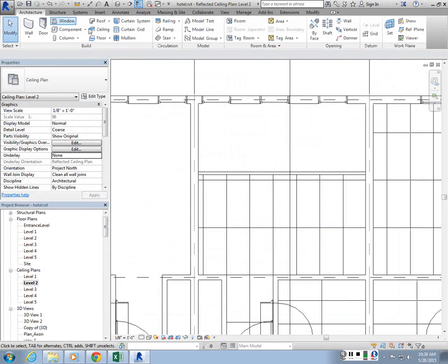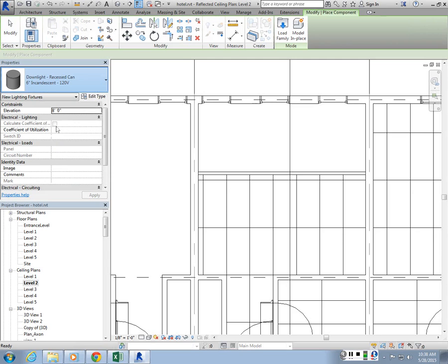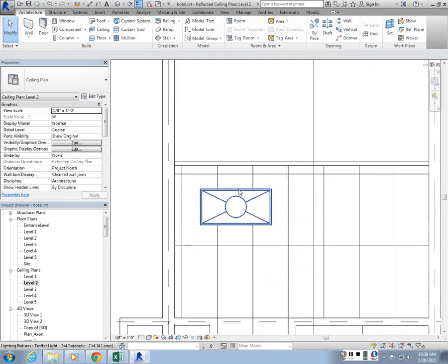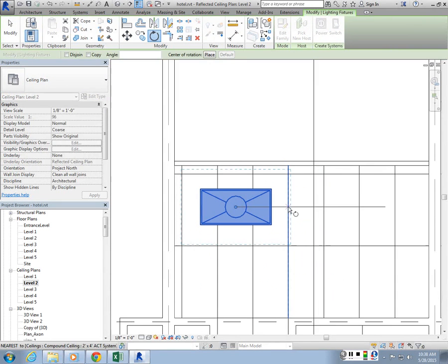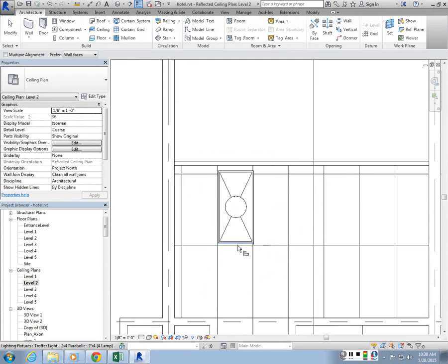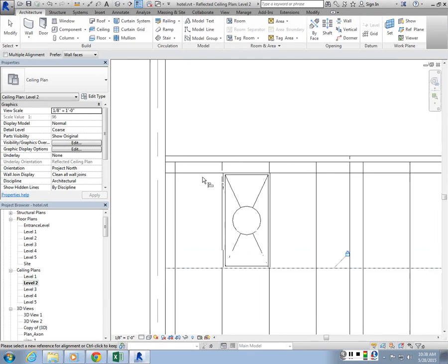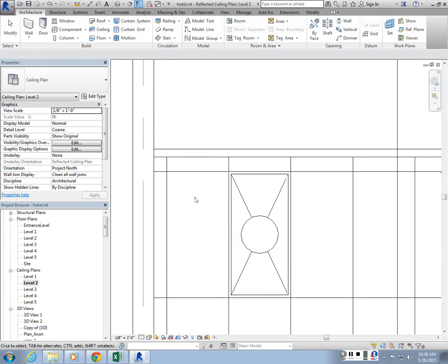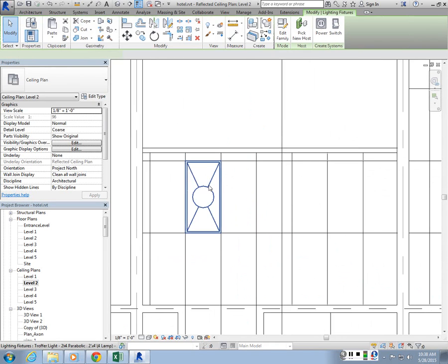And then if you want to include lights, you go to Component, Architecture Component, and lights will be placed here. So I have the floor lamps. I have Troffer Light 2x4. Let's choose 4 lamp, this one. And then I'm going to place this guy here. Type in RO for rotate, and then rotate it 90 degrees. Then you can do the same alignment to the ceiling as well. Right? So you can lock those relationships. So this will be placed.